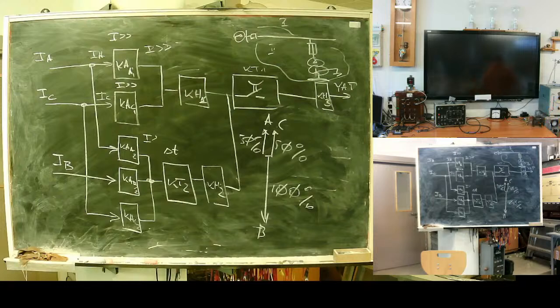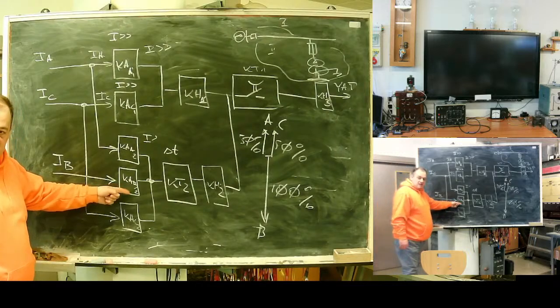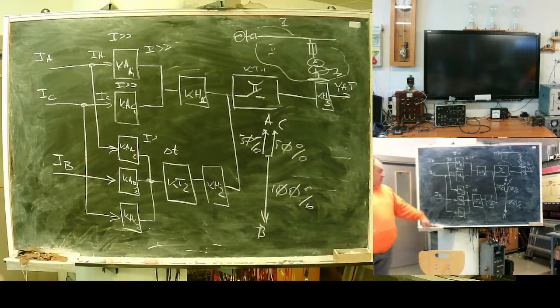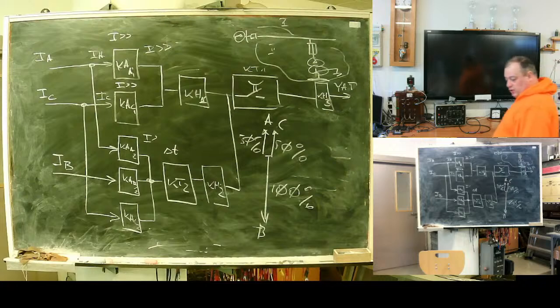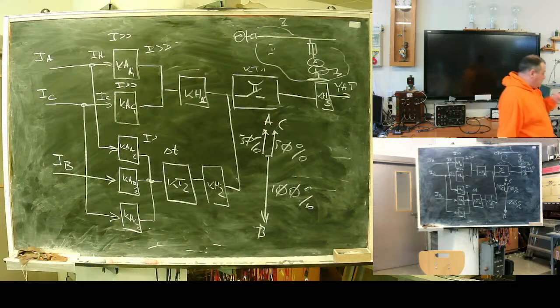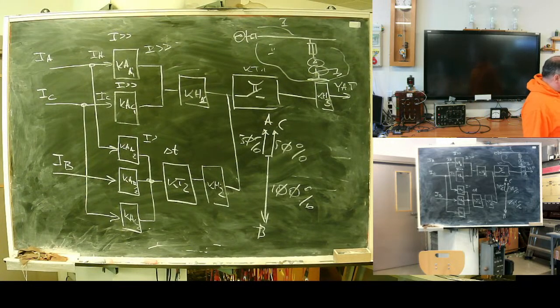To make protection sensitive for faults at the 0.4 kilovolt side, the problem is that we have delta-star transformers. For a delta-star transformer, control of phase B is mandatory. Without it, we can omit it only in isolated mode, a huge exclamation mark: if our network is an isolated neutral network.